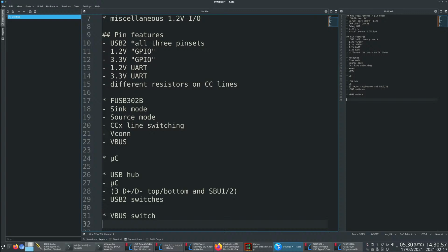But if we are emulating a proper USB PD host, or possibly this is something I need to test, this might be required if we are getting serial into one of the laptops, which actually would try to charge over VBus. One of the questions is whether, for example, if I give it a standard 500 milliamp or 1.5 amp VBus, are they going to try to charge off of that, or will they not charge and just behave as a sort of simple sink in that case? That needs to be tested, because that determines whether you require external power when the upstream VBus is not enough to get a serial port on these laptops, or whether you don't.